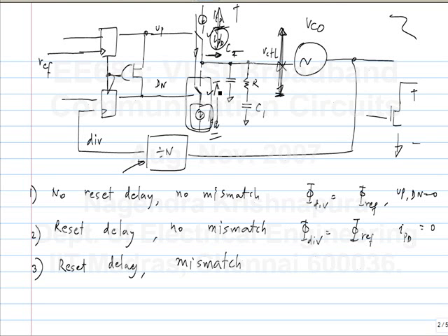How do you connect what? Oh, you have to make the current sources good enough, this and this, and make sure that they switch cleanly. That is, the switching time is identical as much as possible. But beyond that you can't do anything. I mean, there are different topologies, like some advantages to having the current source at the bottom, some to having it at the top. So you have to evaluate it for your case and see which works. We don't have again too much time to go into the circuit design details.